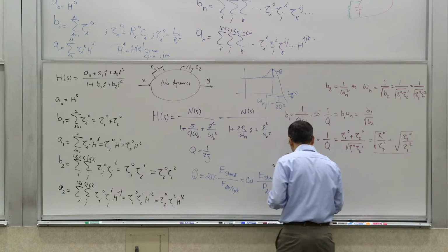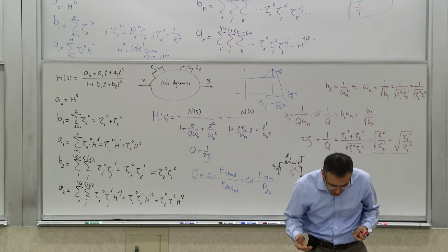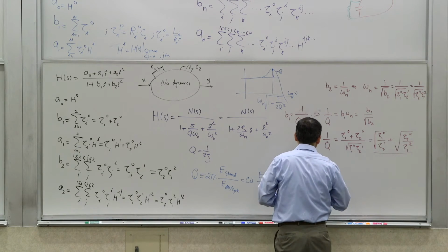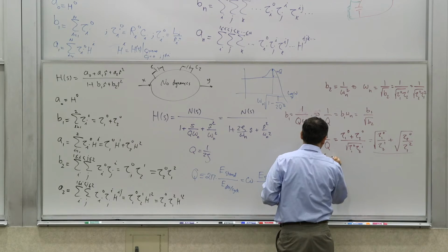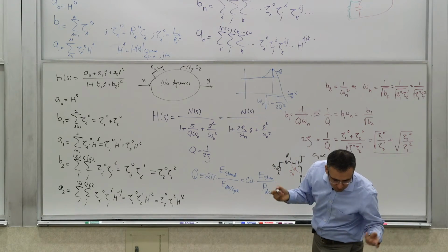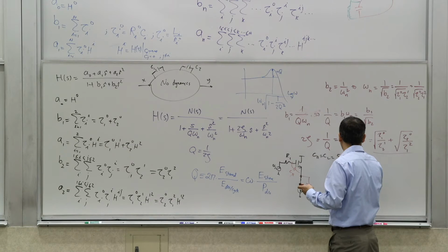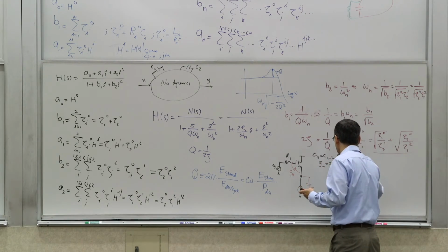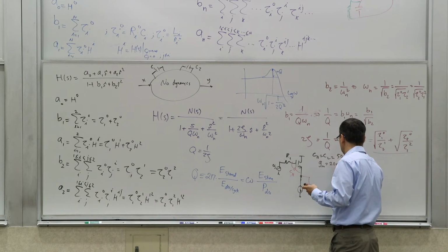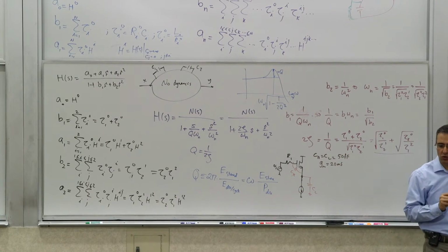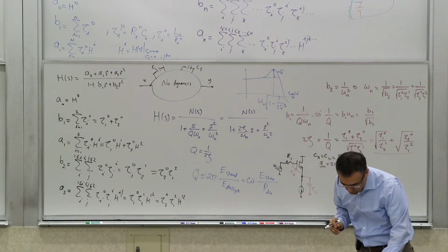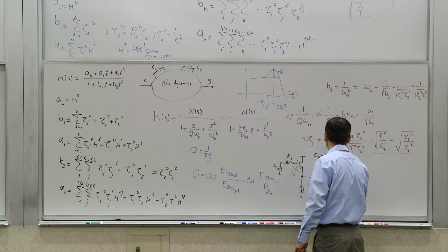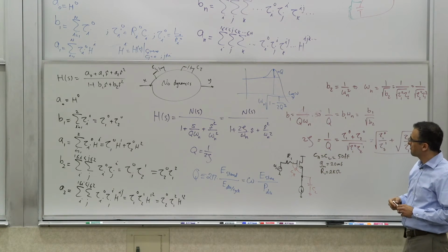Let's just pick some typical values. Let's say C pi equals CL equals 50 femtofarads, and gm of 20 millisiemens, not 2 millisiemens, 20 millisiemens. And then R1 is 2 kilo ohms.